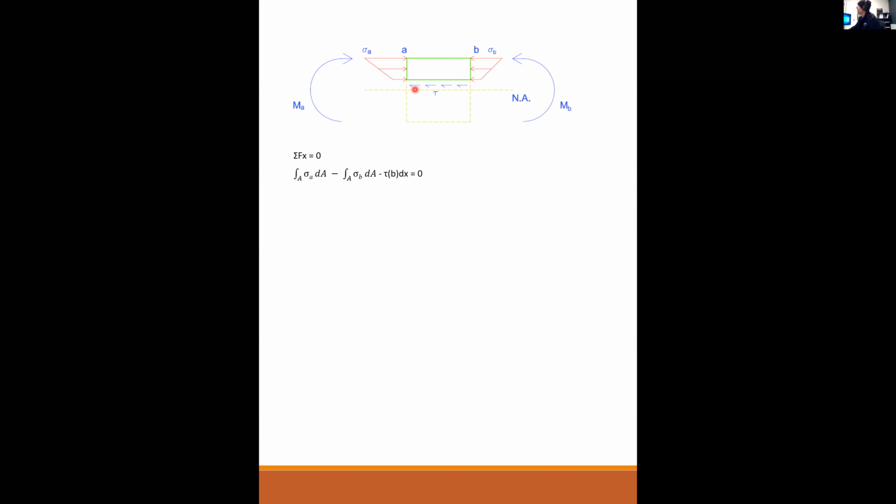That might be a place to check it. Or you could have a flange and a web, like in wood, so they'd be nailed together. And you would want to check it at that interface between the flange and the web where they're nailed together, because that's where it's going to want to fail. So it's going to be more obvious a little bit later where you want to draw that line. Thank you. Yep. All right, so let's get to a derivation here.